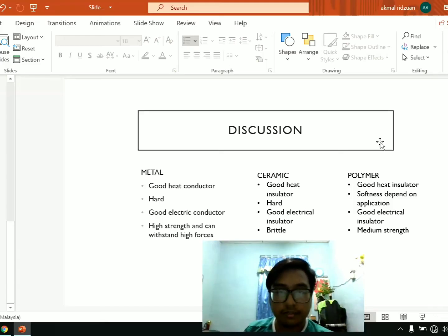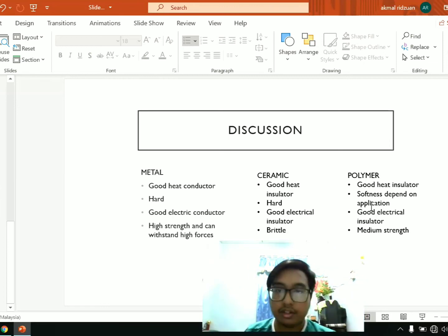Back with me again for the discussion. We can conclude from the experiment that metal is a good heat conductor, is hard, a good electrical conductor, has high strength and can withstand high forces. As for ceramic, it is a good heat insulator, is hard, a good electrical insulator, and also it is brittle. For polymer, it is a good heat insulator, it is soft but it depends on the application. It is a good electrical insulator, and also has medium strength compared to metal.